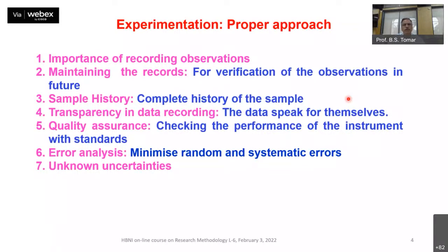Then the quality assurance. Quality assurance means whatever data you are generating, what is the quality of that data? That depends upon the instruments and the methodology that you are adopting. So you should check the performance of the instrument with standards. Whatever data you get out of the instrument, how sure are you that the data is correct? For that, you have to have a quality assurance program. Your instrument must be giving the proper results. For that, they should be well calibrated from time to time.